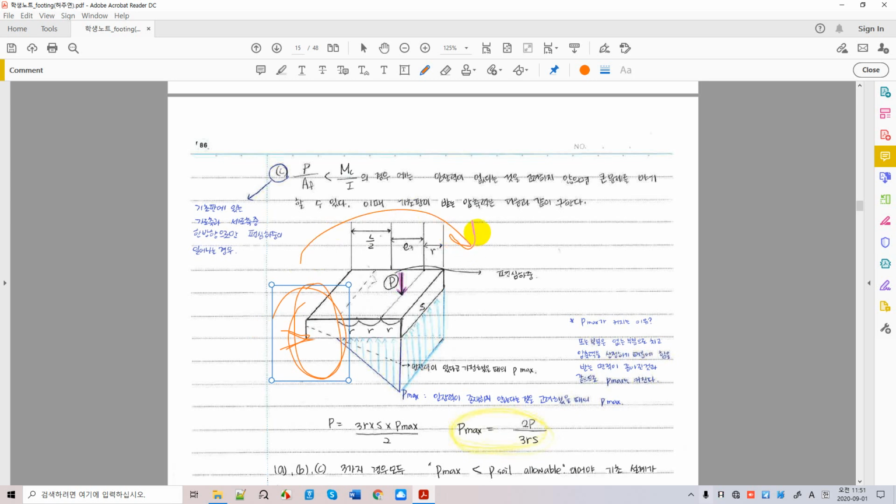Now take a look at the foundations and the soil bearing pressure profiles. As we saw before, we cannot have load bearing capacity in these regions where we have tension. So we only have a compression zone right there where the soil supports the foundation and buildings. This is the pressure block where we can have support for the foundations.